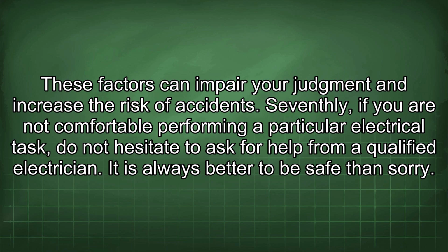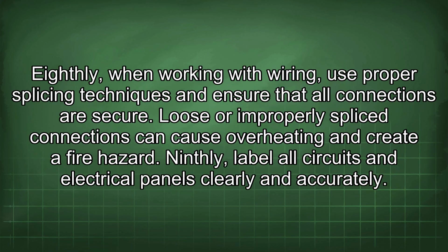Seventhly, if you are not comfortable performing a particular electrical task, do not hesitate to ask for help from a qualified electrician. It is always better to be safe than sorry. Eighthly, when working with wiring, use proper splicing techniques and ensure that all connections are secure. Loose or improperly spliced connections can cause overheating and create a fire hazard.